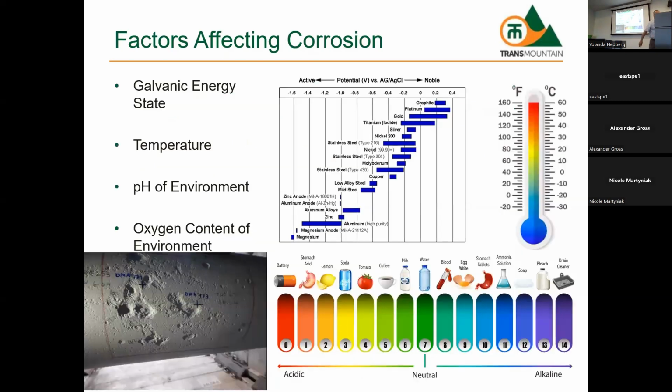On the galvanic series, it depends on the environment, isn't it? So here's aluminum. Zinc. Yes. We have to go more electronegative, but not too electronegative. We only have two choices, really: zinc and magnesium. Magnesium sits at about negative 1.75. The copper sulfate would push the pH too high and cause corrosion of the aluminum, which is amphoteric. So you actually use zinc to protect aluminum.